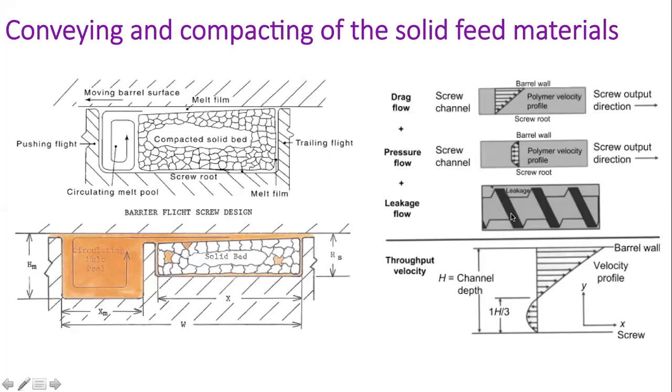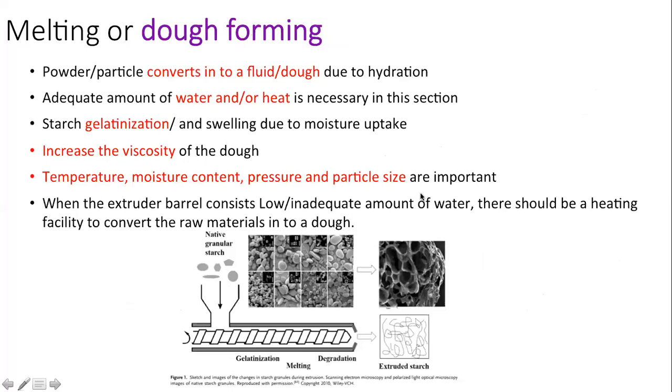So we are going to glue this barrel. We make a groove on the inner side of the barrel, and the screw too. Then we can avoid that leakage flow. Right? So therefore you can see grooved barrels in some high pressure screw extruders. Okay, then as we discussed,